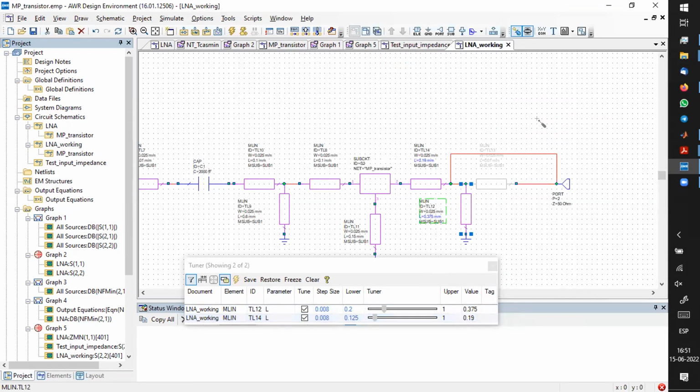Yeah, I would put there a white line that is like a pad where we can wire bond, right? 100 times 100. Yeah, wide, because it needs to be a big one if you want to wire bond it. Yeah, we can add it. There was a piece of a line, but it's a really wide one, but it's a pad. You need to get to the chip, right?